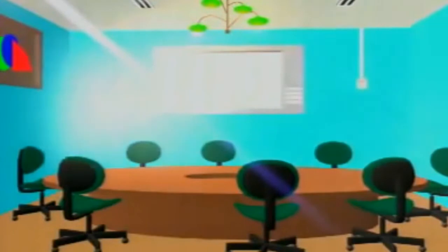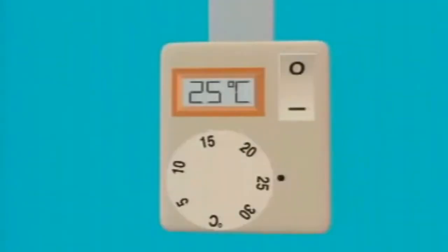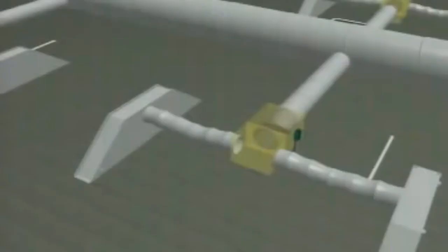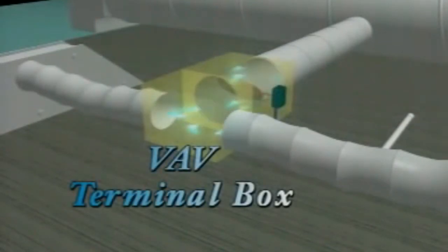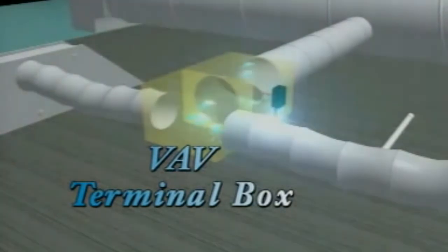In this case, as a result of the additional heat gain in this room, the temperature will rise. Signals are passed to the VAV terminal box, which is used to regulate the supply airflow. The supply air from the AHU at a common temperature is supplied to rooms having different cooling loads. The information that is passed on to the VAV terminal box signals that the room temperature is too high and it needs more cool air to be supplied to the room.